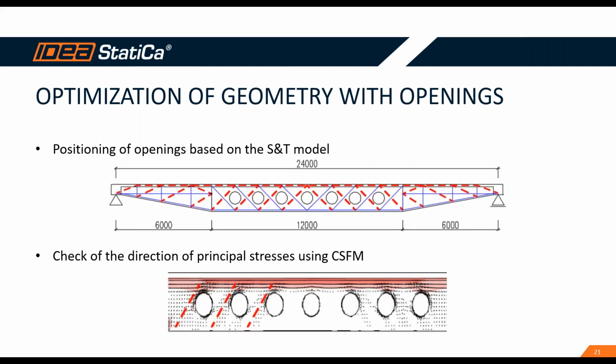The positioning of openings is important, and the engineer positioned the openings according to the strut and tie model. And he also checked the direction of principal stresses in IDEA StatiCa Detail if they correspond with the direction of compressive struts, which were assumed in the strut and tie models, and they compared really well.